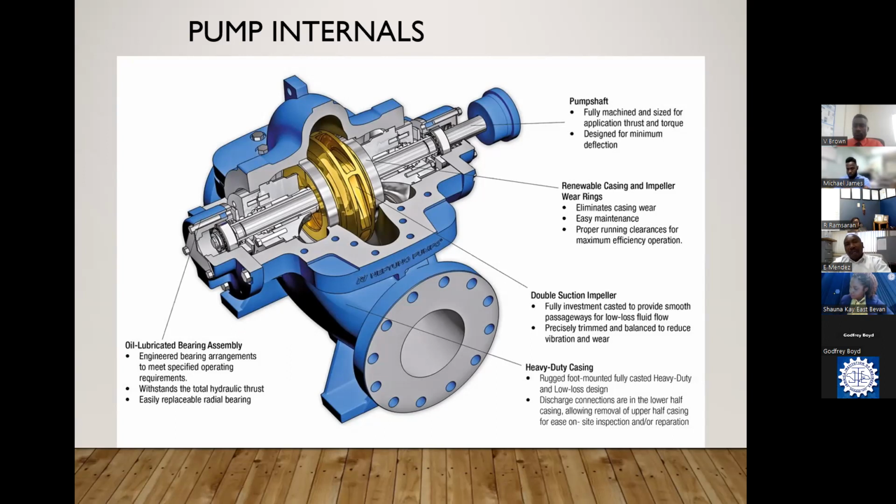When the bearing fails, as you can see there, the clearance from the impeller, that bronze looking middle section, the impeller would move and rub into the casing, and then you lose the impeller, lose the casing, and you have a regular bearing and seals to change out.